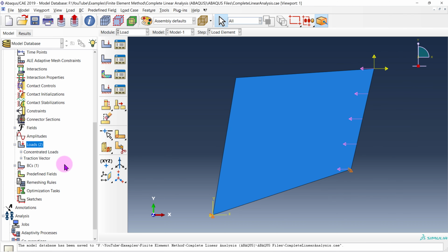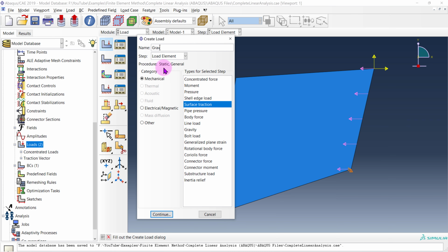The last thing that we have left to do is our gravity load. So I'm going to come down here. I'm going to say load 3 is going to be our gravity load. And we have two different options here. Two different options, guys. So this is going to be completely up to you. One is we can define it as a body force. So remember that in our analysis, we actually defined it as a body force. We called it a body force, but we said, well, actually, this is going to be gravity. Or in ABAQUS, we can actually just define it as gravity. And here's where the differences are going to rely upon. This gravity right here, we're going to input an acceleration. So remember, when we define the material, we define the density, all right?